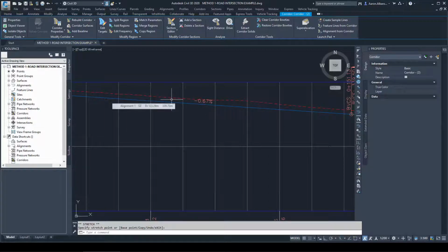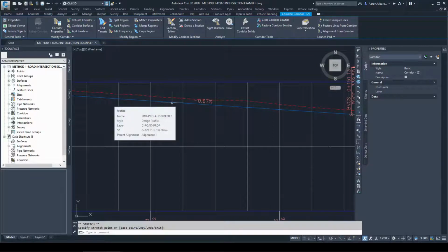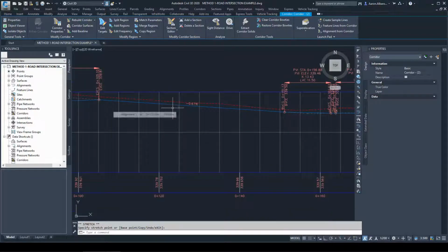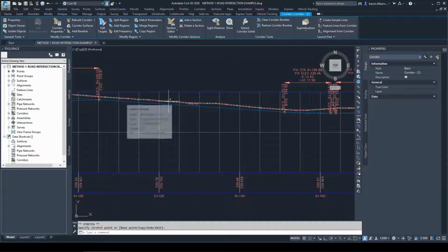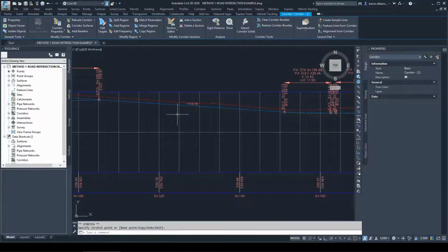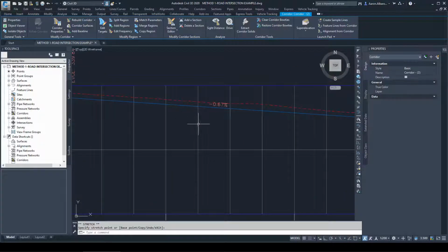Generally speaking, we try to keep the road slightly below the surrounding ground, for drainage purposes. Having said that, the different roads will have slightly different arrangements. We may have some areas where the road is slightly above the existing ground, and that's fine if the topography doesn't allow us to have this arrangement here.